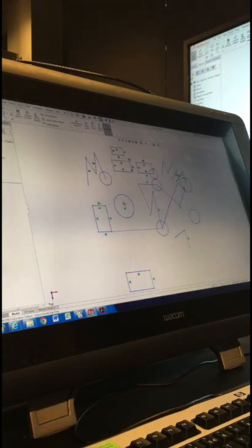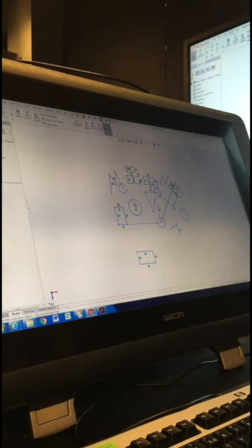So the last thing we'll just touch on here for sketching is how to select. If you just click on any individual line or circle, it'll be selected, it'll highlight as a different color. You'll see it in properties on the side. If you just selected one thing, it'll say circle or line. If you want to select multiple things, hold Control, and then just click on the other items, and you'll see them come up as selected entities in the properties on the left of the screen. When they're selected, if you want to remove them, you can hit delete on the keyboard, or you can sometimes move them all as one group. Not always, but sometimes. But there are some different ways to select things if you want to clear them or change them to construction lines, for instance. The best way is using the mouse.